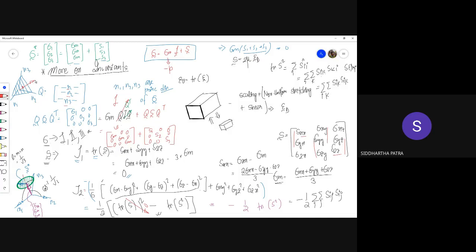So this axis right here makes equal angles with the principal directions, and this plane right here makes equal intercepts with each of the principal directions. So we learned two things. One is that the stresses, that is the hydrostatic and the deviatoric part, can be represented as two orthogonal components. I have been literally mentioning that they are orthogonal, and now we can see in the literal meaning of it how they are orthogonal. They're so orthogonal that their dot product is 0. And what we learn is that the principal directions of the stress and the deviatoric stress tensor are identical.